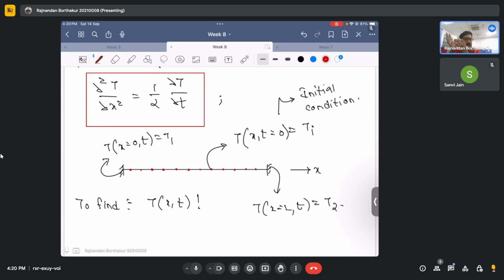If I decrease the number of grids below 1000, my solution will have error. But if I take 2000 grids, my error in the temperature would not be that much, which means I have reached the grid independence stage.